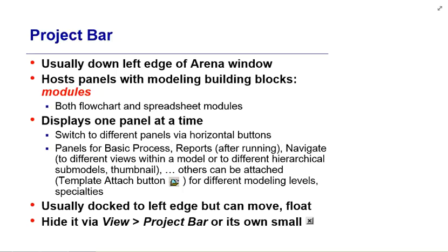which starts off every simulation, and the dispose module, which ends every simulation. In between those, you're going to have a bunch of other things like process modules, decide modules where you want to make a decision on where an entity is going to go. Things like batching and separating, where you can batch a given number of parts for some specific process. And then when you're outside that process, you can either leave it as a batch or you can separate them back into individual entities. The clone module we've not used yet. We'll get to that later.